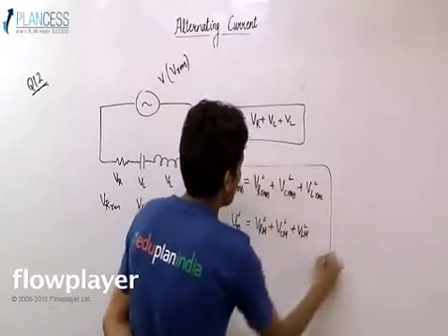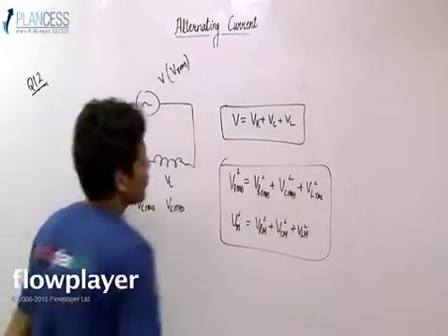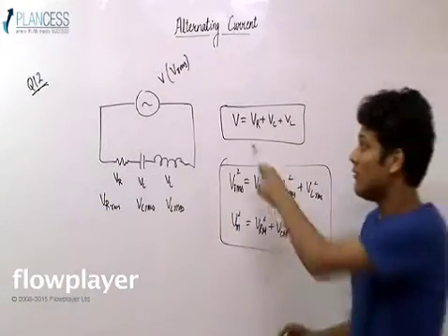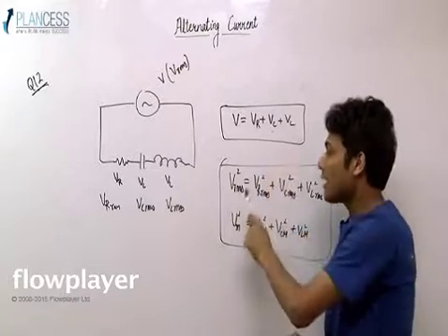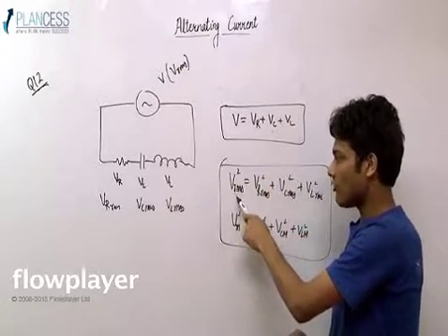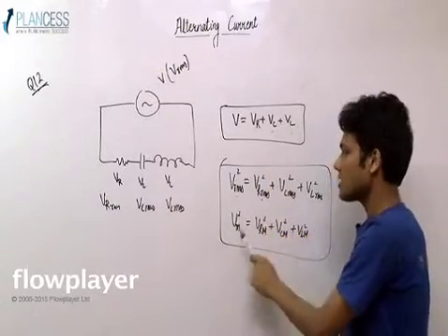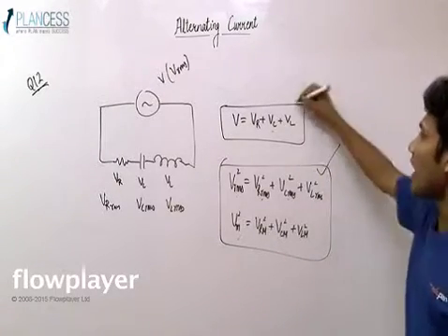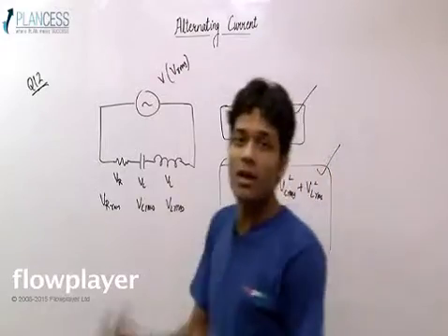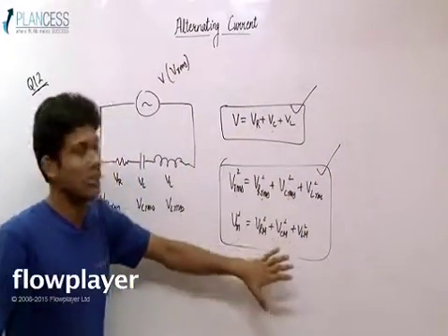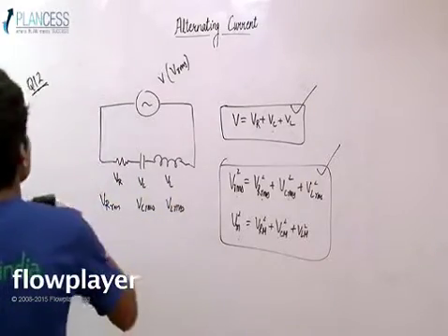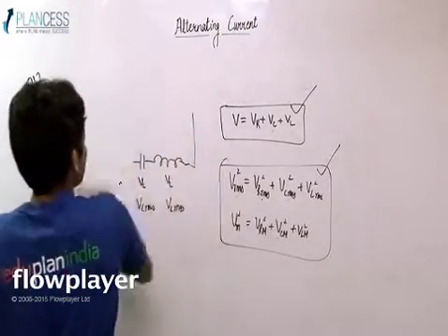So this is really a great point of confusion among students. The instantaneous voltages satisfy V equals VR plus VC plus VL. But for RMS we have the square condition, and for maximum values also we have this equation. So this is correct and this is correct, and do not get confused between these two things. Okay, so remember this. So this was our question number 12.